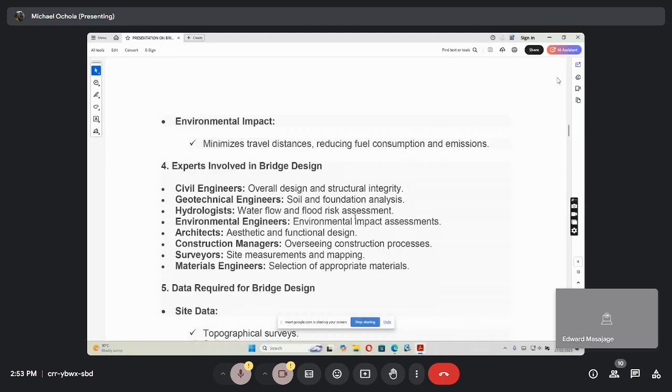What is it? If the soil condition below 10 meters and beyond is not good, and rock is maybe 20 meters down, that's where now you come up with what you call pile foundation or any deep foundation you need. If it is shallower, then now you may decide to go using spread footing and other types of footing. So the only person who gives you that knowledge for you to be able to model and design is the geotechnical guy.